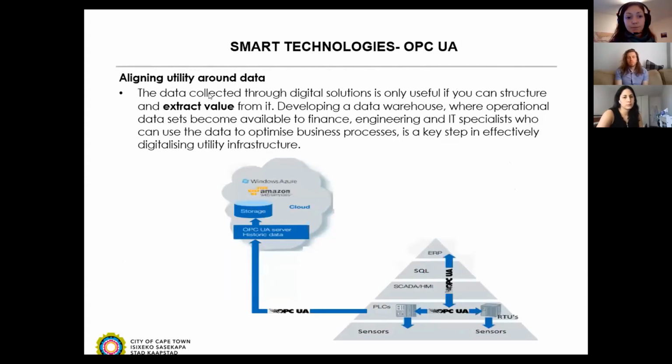Here I show on this slide where you could have sensors moving data through the OPC UA all the way up to your ERP, or you could have your sensors showing their data with your SCADAs. Currently, we've got standalone systems that have various proprietary protocols, and it's difficult for us to have systems talking to each other, and we're trying to move away from that.